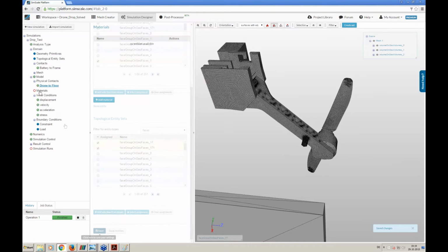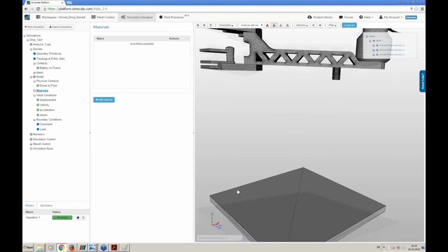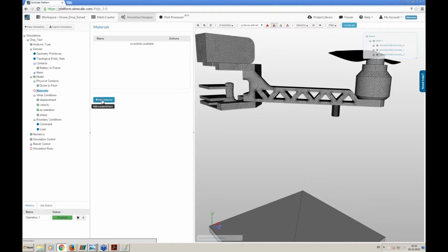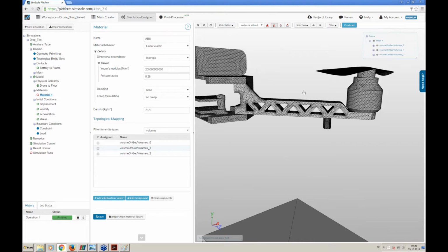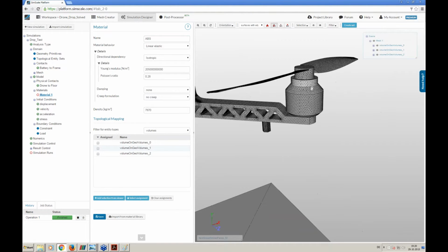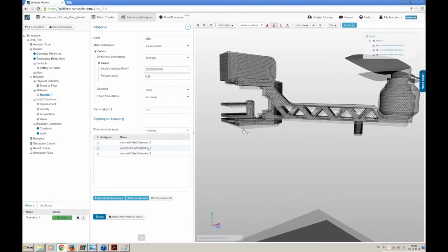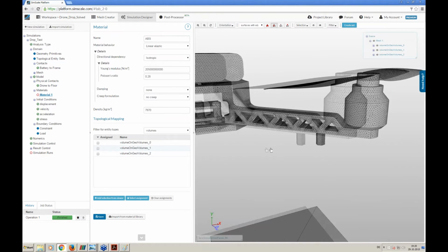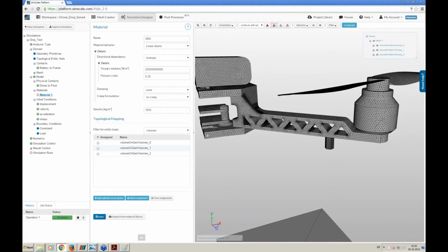Now we have the second contact, and now we have to define the materials which we want to use. And this is quite similar to last time, but let's do it again. So let's start with the ABS material. This is the polymer which this drone is made of. We would say we would print this frame with a 3D printer. For sure the engine is not made of ABS, but this is a simplification we made for this first step. Later on, in level 2, you will use a more complex model where you have the engine as parts, the battery, we also have screws, etc.